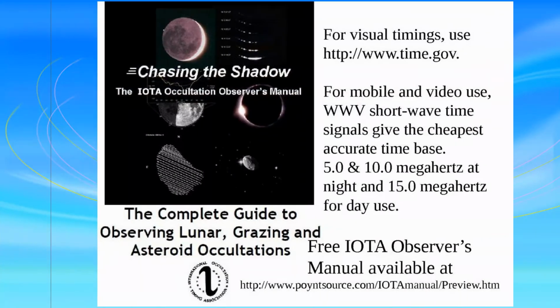The easier way is to use a shortwave time signal from a shortwave radio. It's the cheapest way to get a really accurate time base, and you have to have one that can receive at 5 and 10 megahertz. Those are the best frequencies at night. Usually 5 is the most important, but 10 is often best during the dawn and twilight hours. That can be the case if the transmitting station, which is in Colorado, is in twilight and you're in complete darkness. 10 will probably come in better than 5 at that point.